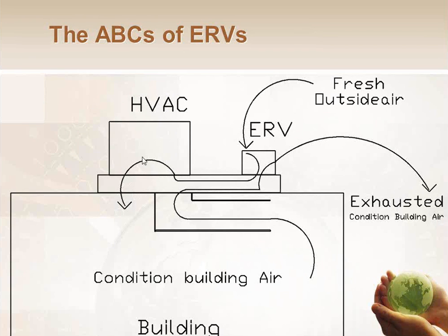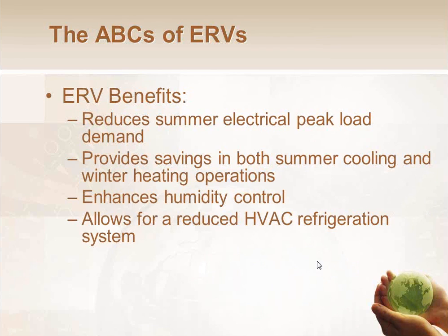I could basically put these two pieces of equipment together, either one giant unit with both pieces built into it, or like we're showing here, two units side by side, and I've got some common ductwork between the two of them. We'll explain more about different ways to do that as we go through here with lots of actual real photos of installations. We've got to get the exhaust air near the outside air. That's what we've got to do.